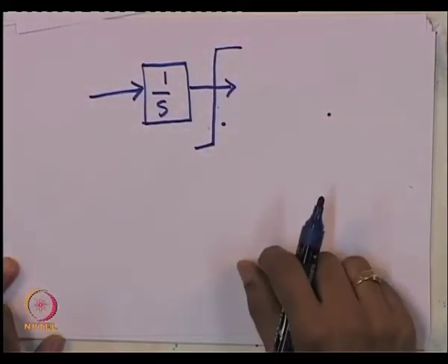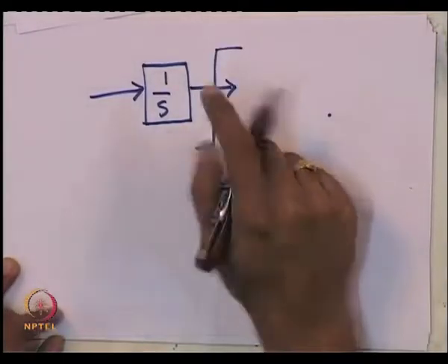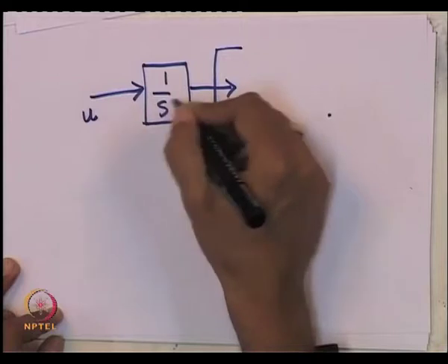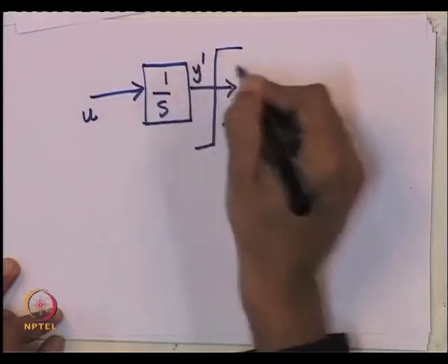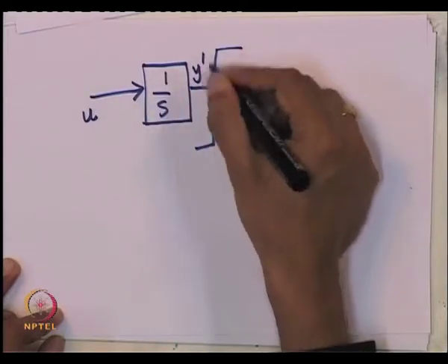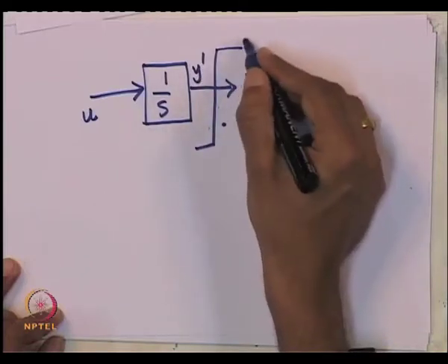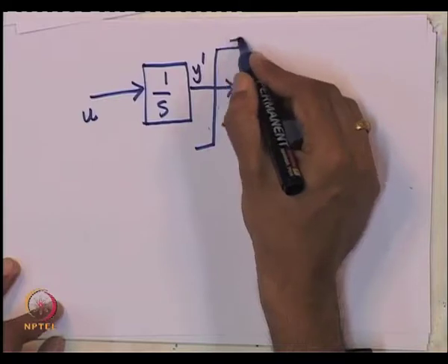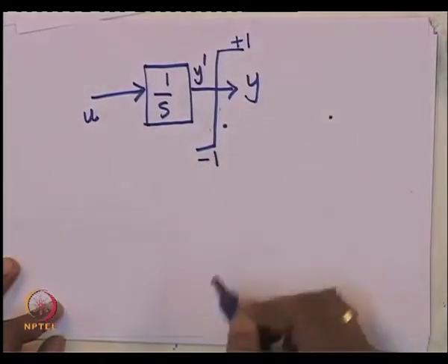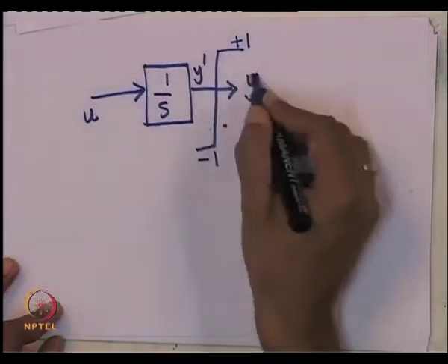And I try to limit it. Okay. This is a soft limit. So, if I got an input u, it will be integrated in order to get y dash. y will be the clipped value of y dash. Of course, if y dash does not exceed any of the limits specified here, for example, +1 or -1, this is an example of a limit, in that case, y dash is equal to y.